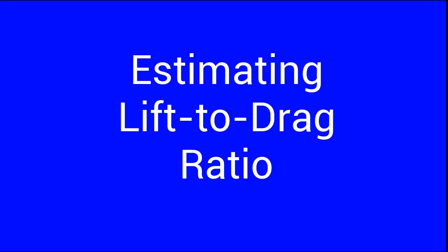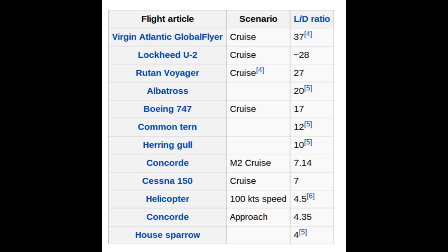As far as lift-to-drag ratio goes, there are simple ways to estimate just from the aircraft type. This is a table taken from Wikipedia. If you match up the kind of airplane or the basic shape of the airplane with what you see in the table, you might get a decent estimate of an achievable lift-to-drag ratio in cruise.